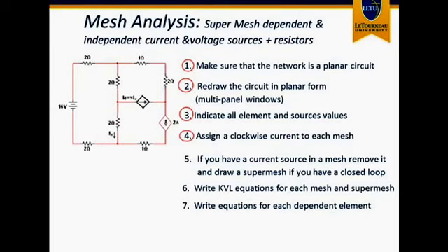Fourth, we will need to assign a clockwise current to each mesh. So mesh 1, we assign current I1. Mesh 2, we assign current I2. Mesh 3, we will assign current I3.